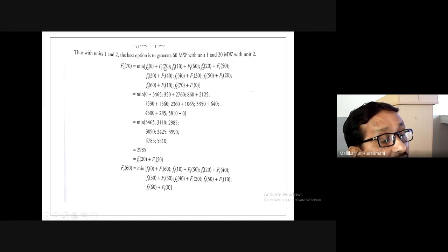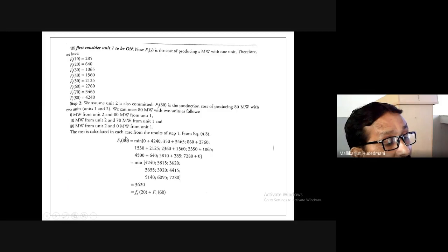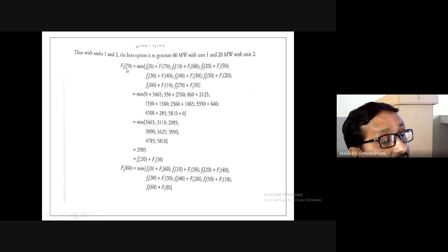So similarly, I have different sharing combinations from machine 2, machine 1 for a load of 70. Earlier I did a load of 80. If I do a load of 70, similarly I have information for production cost. Production cost I will place here. When I place the production values, I will get the minimum combination of this as 50 megawatt from machine 1, 20 megawatt from machine 2 to fulfill your 70 requirement. This is a recursive process. Why I am going in reverse, you may see.